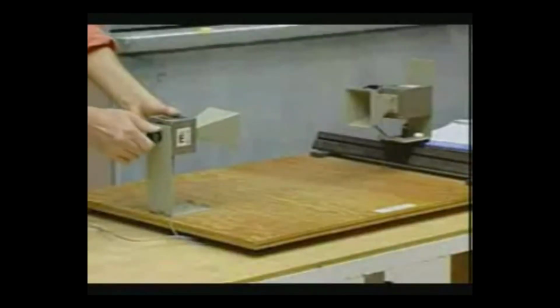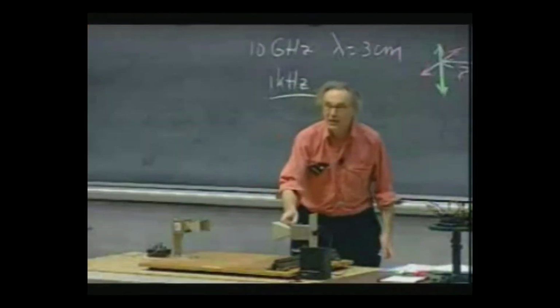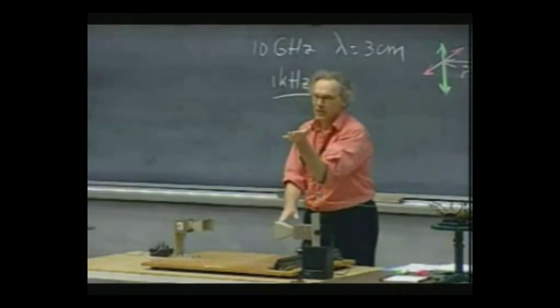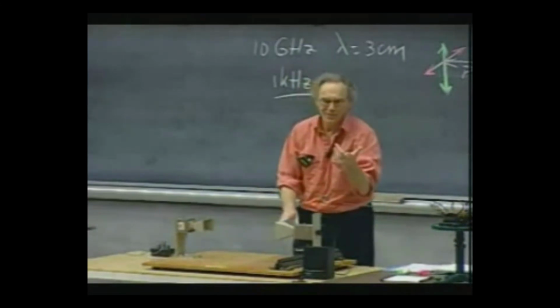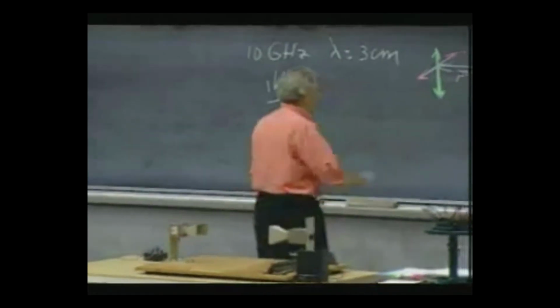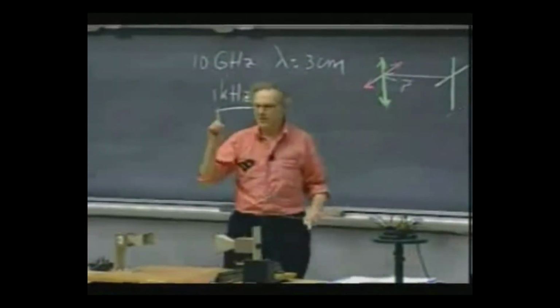And it stops. So now the electric field goes like this. The wire here, the antenna, is like this, and the wire says, sorry, I can't hear you. But all I have to do now is rotate the receiver 90 degrees, so I can rotate this antenna and put it vertical, and then, of course, it's happy again.